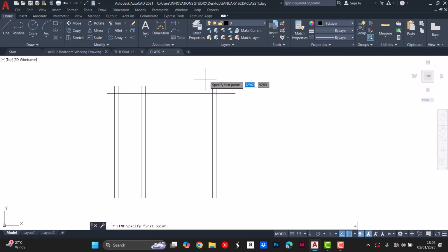Now I'll turn it off and you see what happens. You see, you don't even know if your line is straight. So you have to be following your angles. But the moment you have it turned on, when your line is straight, there's a green dotted line that appears. Okay, so back to business. Then you click on offset. When you click on the line, you click on offset.